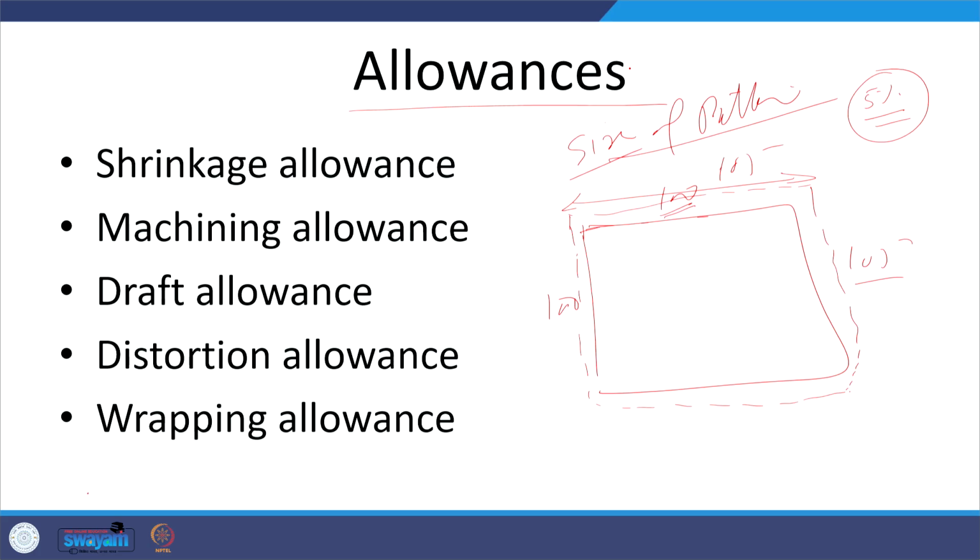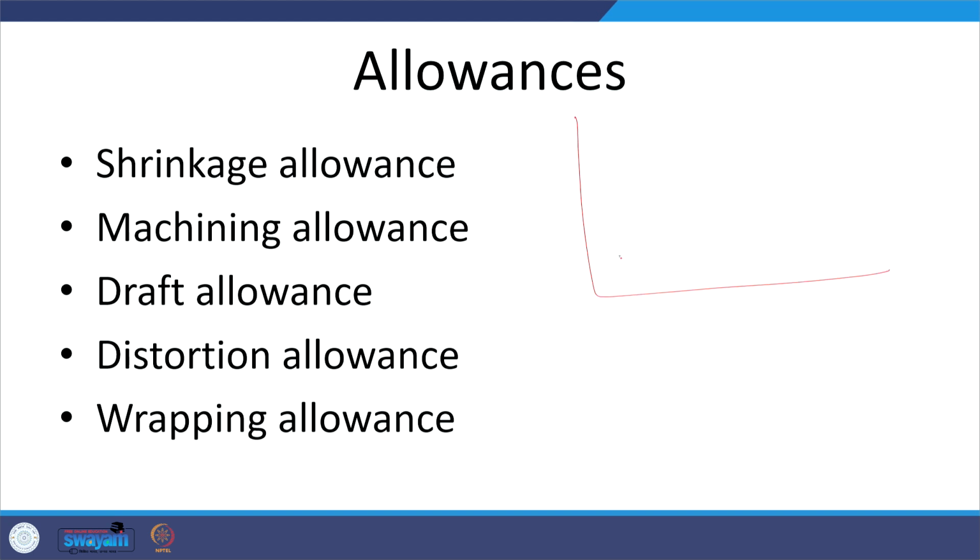Okay, so here, if we see which aspect is taken care of, say we know that this is the temperature on the y axis and on the x axis there is time. So if we try to draw the cooling curve, it comes like this. So this is the liquid state, this is the undercooling zone, this is where solidification starts. Okay, and then here solidification completes. Okay, and once the solidification completes, then we will have cooling down to the room temperature.